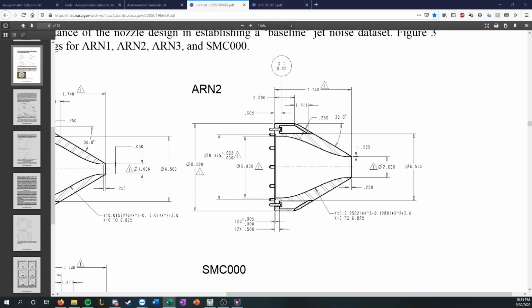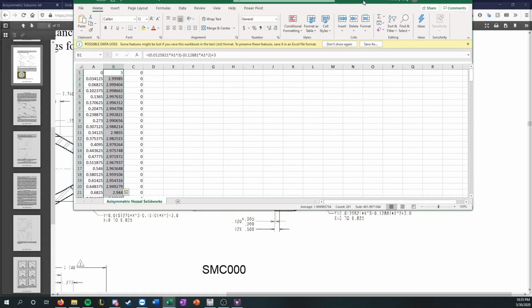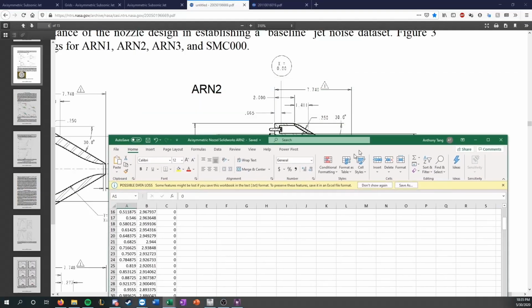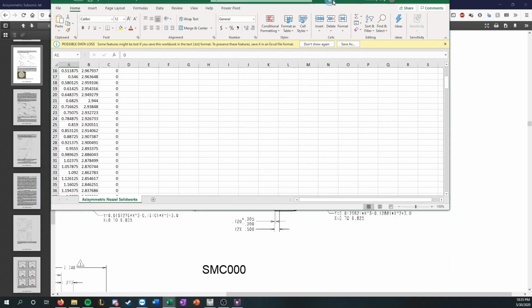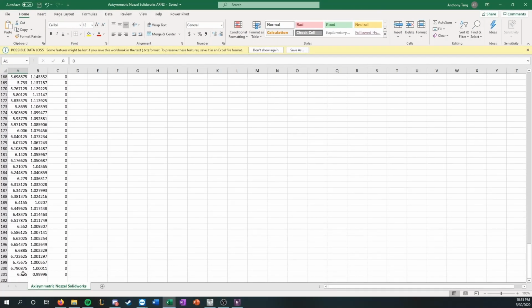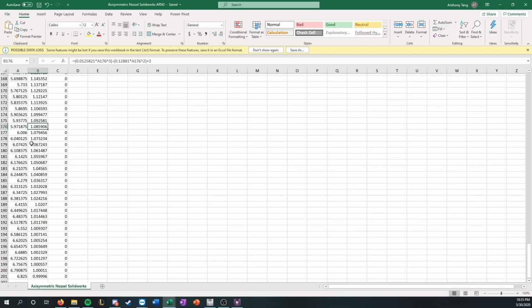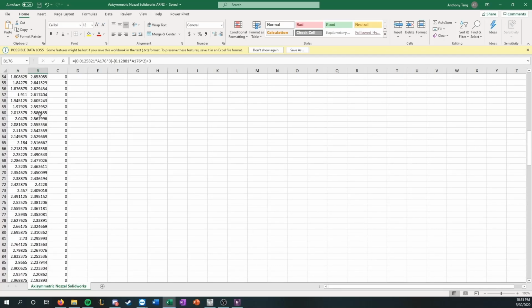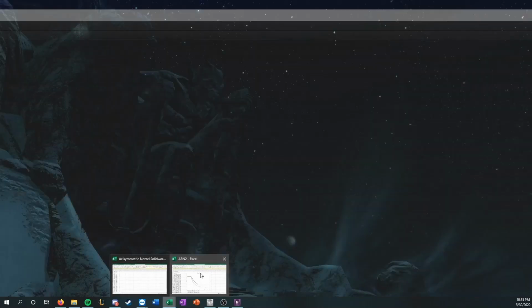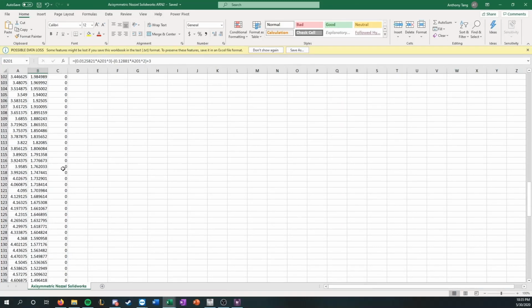Oh, here we go. So on x, I simply did 0 to 6.825, as it said to use. I created 200 points to be exact, from 0 to 6.825, and I plugged in this equation. That's the equation it gives. And it gives me these values from a height of 3 to basically 1, which makes sense because the radius should be 1 so that the diameter is 2. And then these points are created such that they can actually be put into SolidWorks.